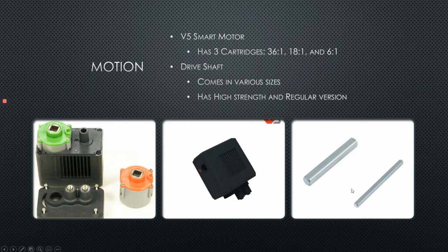A disadvantage is that it may bend or break easily. An advantage with the high strength is that it won't bend or break easily. It's stronger, it's more firm. But a disadvantage is it's really thick, so it wouldn't fit in your regular structural C channel, L channel bar or plate. You would actually have to drill another hole in that C channel in order for it to